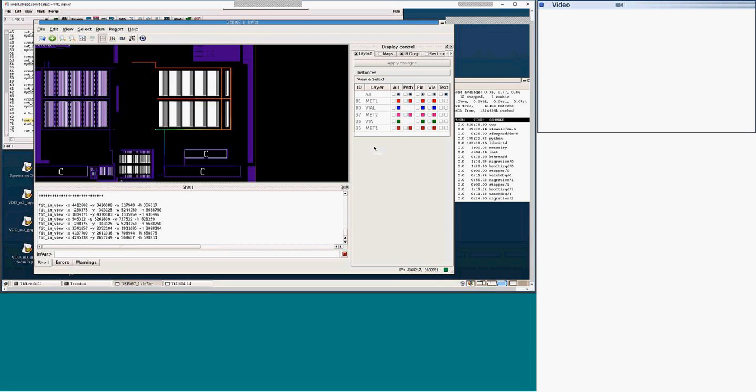If you expect to see some delays, I would recommend you use Spice simulation alone and use detailed, non-reduced parasitic extraction for this, because what we measure and simulate is IR drop on metal structures and via structures. For delays, I believe the Spice engine is the tool that should be used. We just reuse results of electrical analysis.